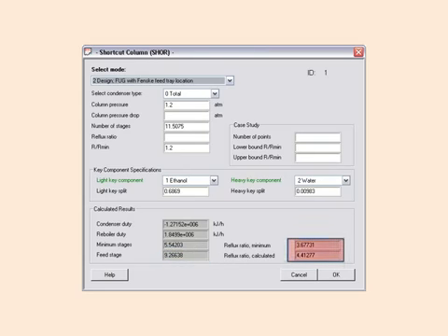Our minimum reflux ratio is calculated to be 3.7, and the reflux ratio using our R over R min of 1.2 specifies that our reflux ratio is 4.41. So in total, our column design would have 12 stages where we would feed in at stage 9. Now in ChemCAD, it counts the condenser and the reboiler as stages. So technically, we have a column with 10 trays and a condenser and a reboiler, and this would give us the basis for designing our column.